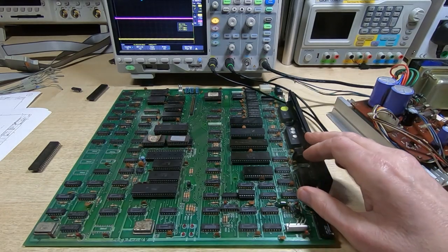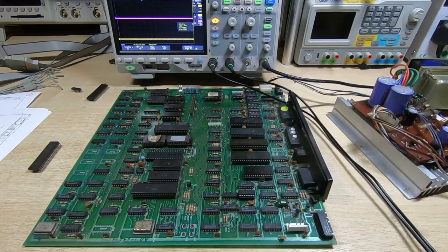Okay, we'll try and power this back up. Like I said, I don't know if these actually work, so this might still fail. So RAM test. So that test seems to have stalled. It's getting further than it was. It still may be because the SIOs are faulty, or it may be because it's waiting for a response from the 6502 to one of the test steps.